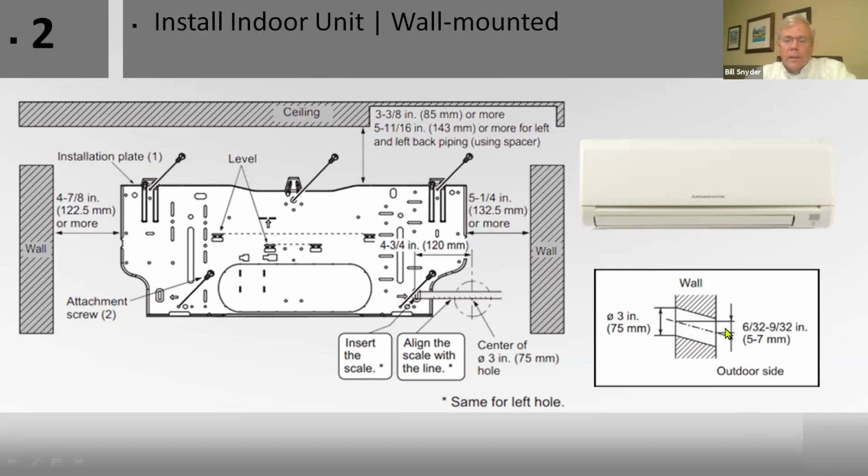Also in the summer, if this is open, hot, humid air can come in through the back, actually get sucked in through the fan here into here, and then you get humidity issues here, and it can form organic growth. I say organic growth. We never say the word mold to a homeowner. It's organic growth or some sort of buildup in there. If you say it's mold, some homeowners will go, can you clean it? And some will freak out because mold scares a lot of people. So just be very careful.